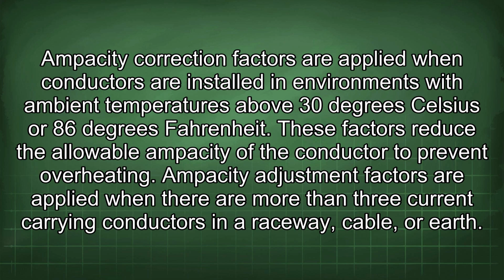Ampacity correction factors are applied when conductors are installed in environments with ambient temperatures above 30 degrees Celsius or 86 degrees Fahrenheit. These factors reduce the allowable ampacity of the conductor to prevent overheating. Ampacity adjustment factors are applied when there are more than 3 current-carrying conductors in a raceway, cable, or earth.